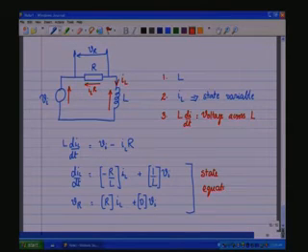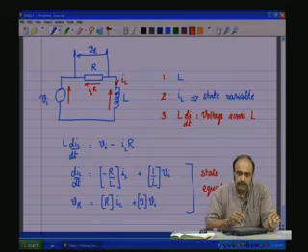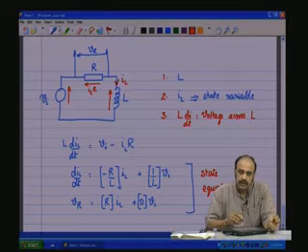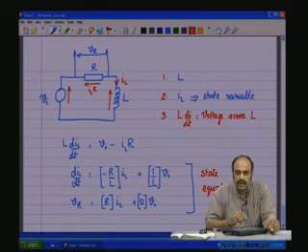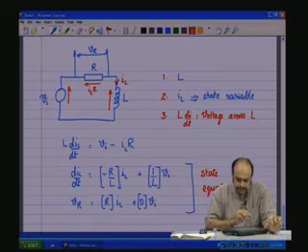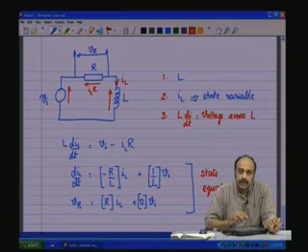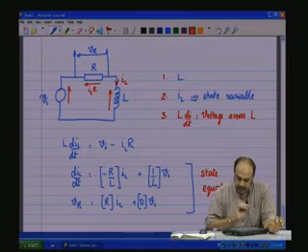You see, it is so simple. Actually, whatever be the complexity of the circuit, you just have to follow these 3 steps. Step 1, identify the energy storing elements. Step 2, identify the state variables associated with these energy storing elements. Step 3, with no particular order, starting at any particular energy storing element, the equation describing its dynamic behavior can be put down, and then followed by the equation describing the dynamic behavior of all other energy storing elements in the circuit. So, that is the method that we will be following.